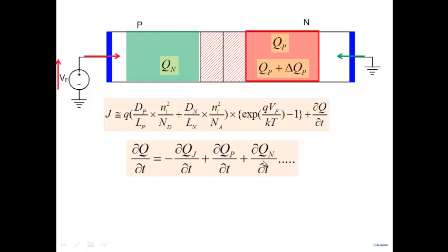And therefore, now, many times, what is very confusing for people is that I have holes here, but they say the region is neutral. And neutral region, well, overall is neutral, and therefore, you have no charge. I mean, it should not contribute to capacitance. But it's a flawed argument, because if you look at the depletion region also, overall it is neutral, right? A positive charge, negative charge. Overall, any capacitor is neutral. A positive charge on one plate, negative charge on the other plate is overall neutral.